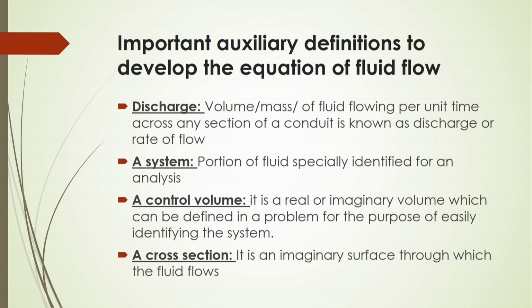Before analyzing the equation of fluid flow, you have to define a system. Sometimes you have to consider a portion of the fluid that is specially identified for an analysis. Also you have to consider a control volume, a real or imaginary volume which can be defined in a problem for the purpose of easily identifying the system. Also the cross section is an imaginary surface through which the fluid will be flowing. So that also should be defined in your analysis of fluid flow.